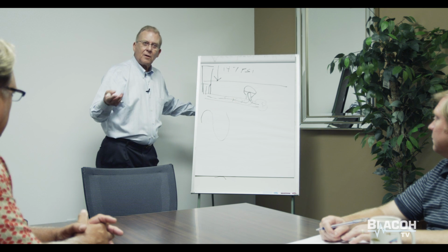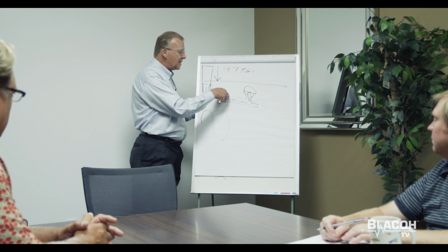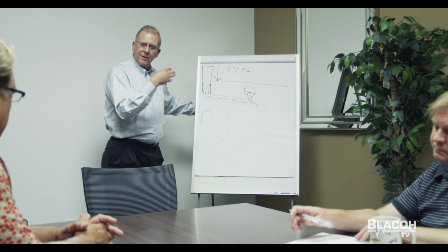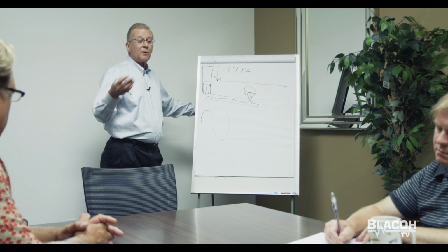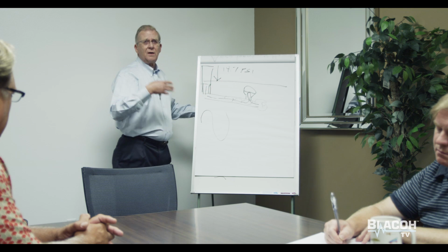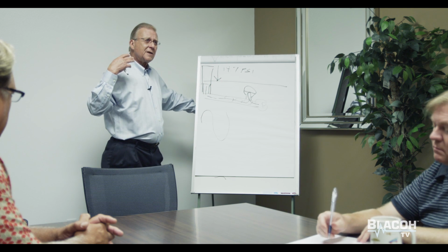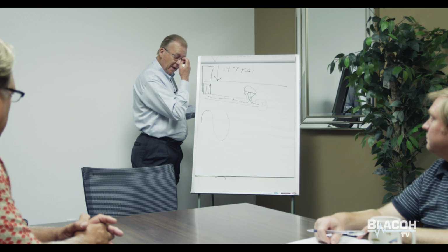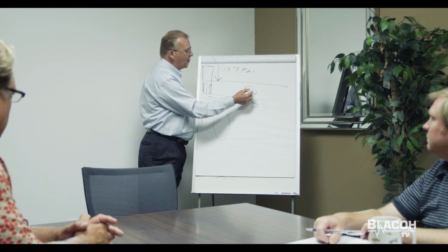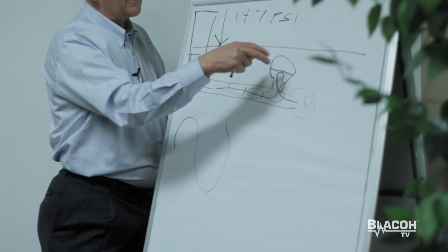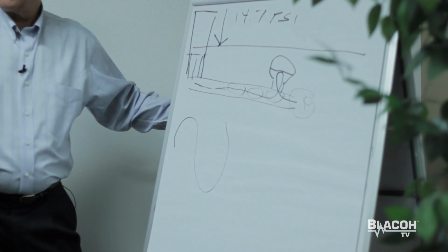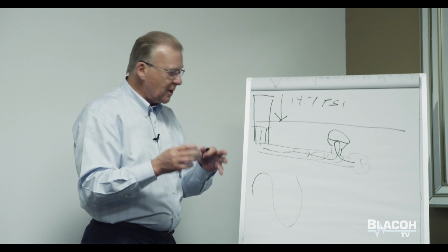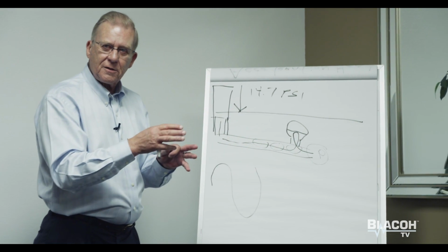It can damage components and pumps, it can damage gauges, gaskets, flanges, threaded joints, and can cause all kinds of problems because that pressure spike can be 4 to as many as 8 times greater than the flowing pressure. Well, now we charge this inlet stabilizer differently, and it acts like an accumulator and stores that energy much like it does on the discharge side.